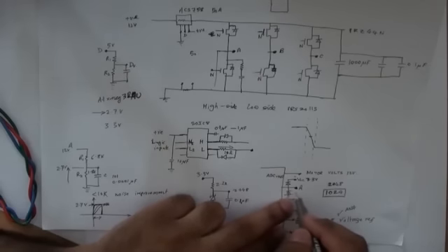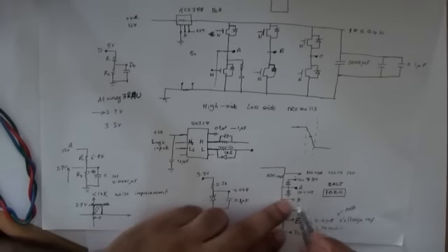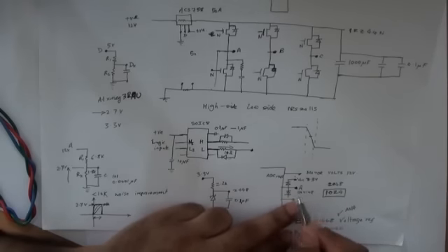So generally, if you use a 1N4148, which is probably not suitable because you can have potentially large currents, so you want to use a more heavy-duty diode, but perhaps a faster one. But typically they have 500 millivolt voltage drop.